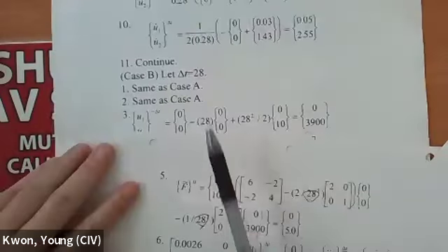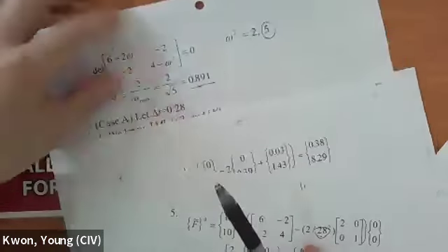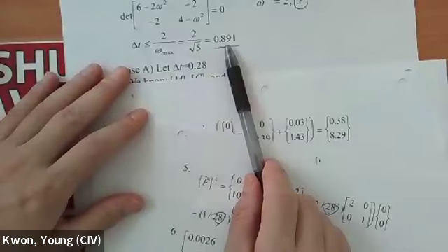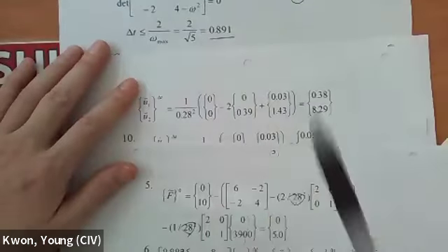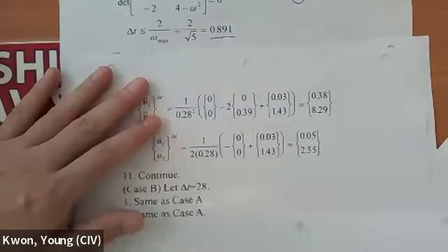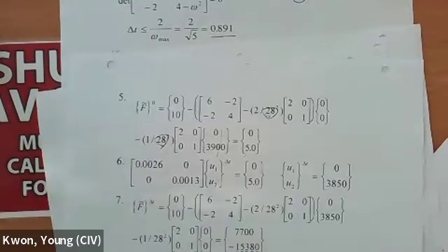And if you pick one closer to your critical value, which was 0.891, so if I use, for example, delta t of 0.9, then what happens? It's going to blow up very slowly. So in the first 100 or 200,000 steps, you may not see the blow up. But as you continue the calculation, a million times, then eventually you see that the solution blows up.